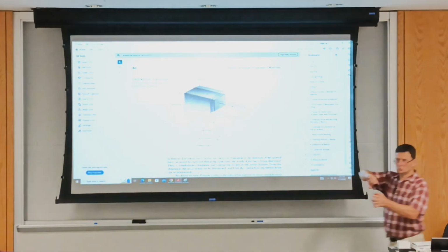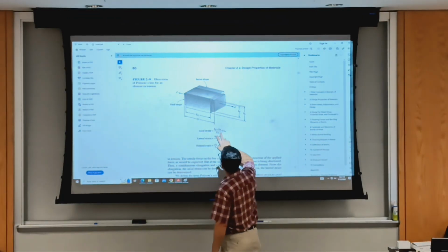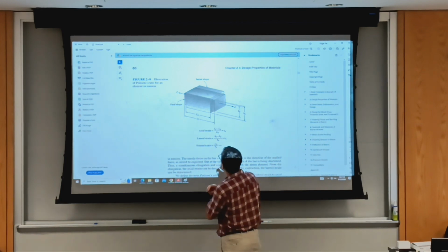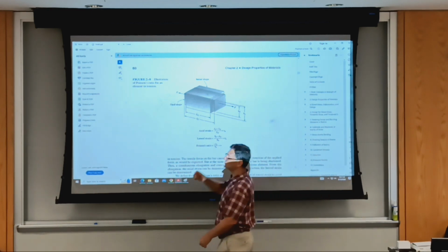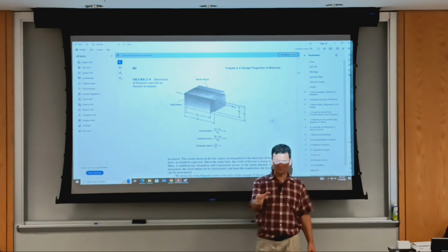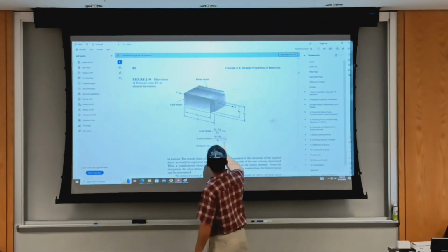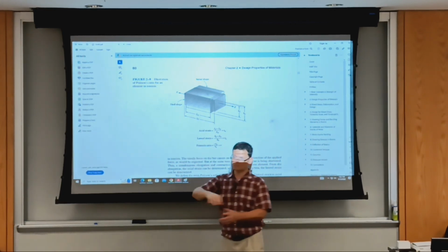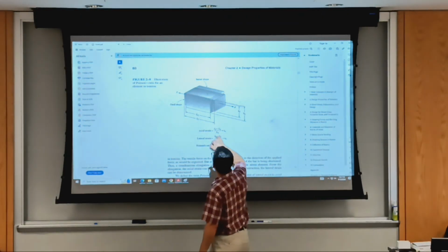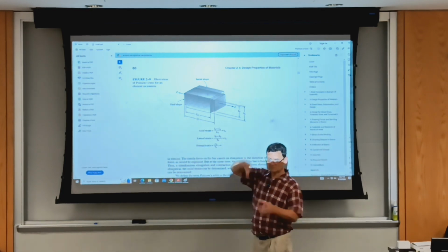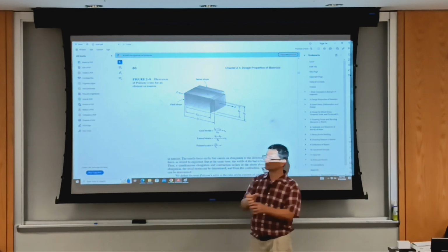You saw in the YouTube video that as you stretch the specimen, it shrinks, right? So you can also record, now that it's commonly done, the lateral strain. It could be done on a round specimen, could be done on a rectangular specimen. So you measure initial dimensions, diameter or width, and then you record that over time, and you calculate a lateral strain. This is due to volume conservation, but there's more to it. The lateral strain goes down as the axial strain is increased, the reduction in diameter throughout the specimen. That's before the necking develops.